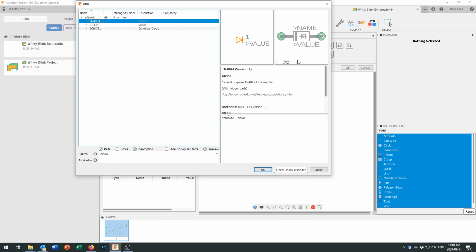A lot of the diodes that we've got in the shop are sometimes a little bit bigger than that. I'm just looking at the spacing right there, and the grid is 10 millimeters. Yeah, 10 millimeters is 1 centimeter. Diameter 2.54. Those look like appropriate dimensions for the diodes that we're going to use. If you've got any doubts, you can take a diode off of an existing board that you have and use your vernier calipers and take a measurement off of that. But this should be a great diode to add to our board, the 1N4004.